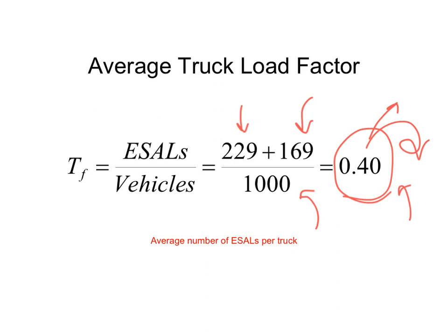This factor here is known as truck load factor, or in terms of IRC, this factor is known as vehicle damage factor. We'll use this vehicle damage factor in our various design problems when we see how to design a pavement using the IRC 37 code.